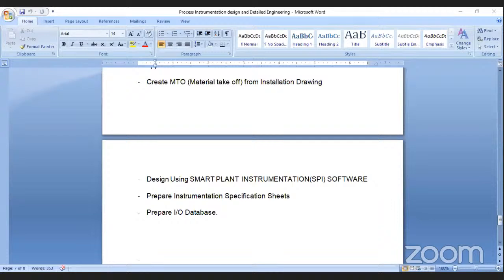System engineering is basically the selection of these IO modules. How to select that? Based on the number of IOs, of course, which is important, and the types of IOs are also important. Based on that, we will select them. Then enclosure rating is also important.